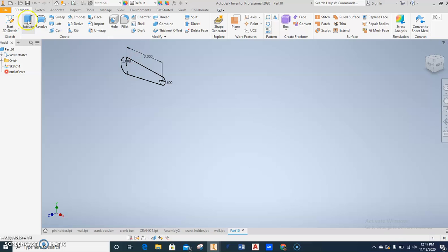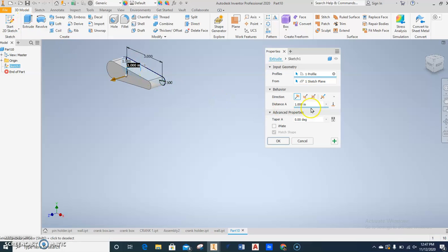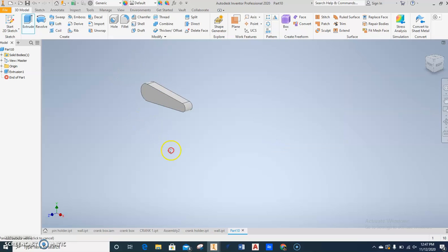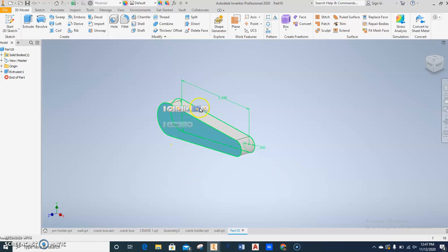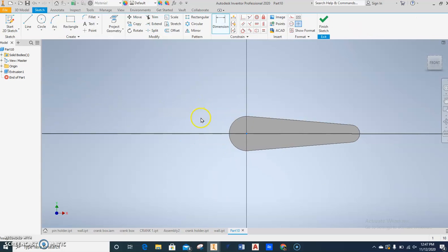You're going to extrude this thing 0.5. So 0.5. Press enter and OK. All right, that's set up. So next we have to make the actual shaft that goes onto the crank handle. So in order to do a drawing on a different surface, you click on it, and then if you move your mouse over, the icon to the very right of those 5 icons is called Create Sketch. Click that, please.